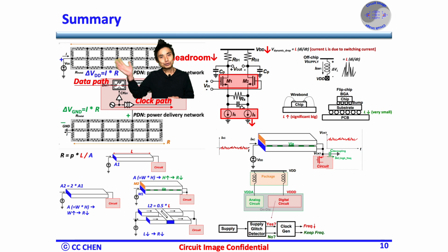Therefore, in digital gates, a low supply will either slow down the clock path or the data path in a flip-flop system to result in a timing variation, such as the setup or hold time variation. But in analog blocks, a low supply voltage will consume the headroom of any current source in biasing or amplifier to cause accuracy degradation.